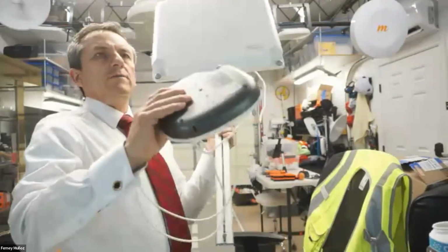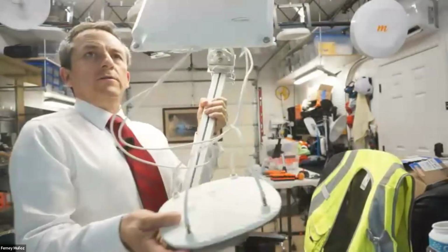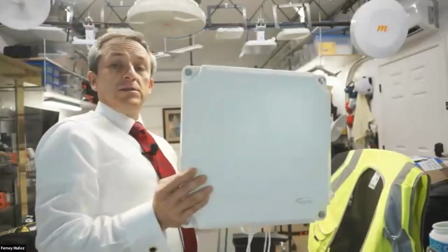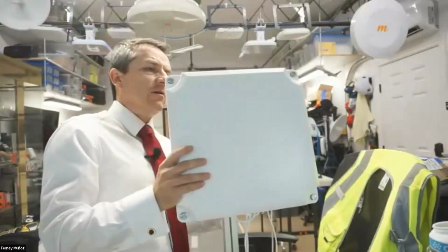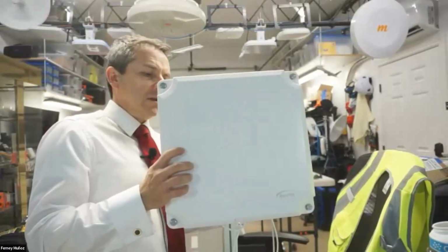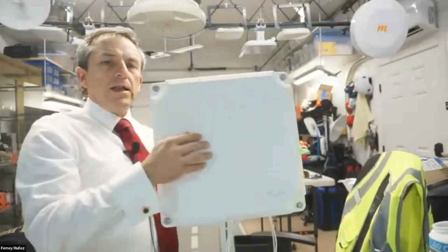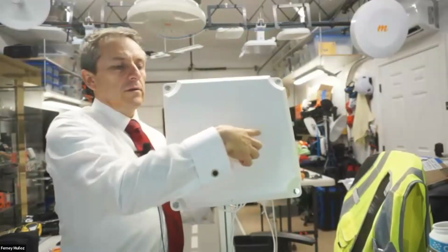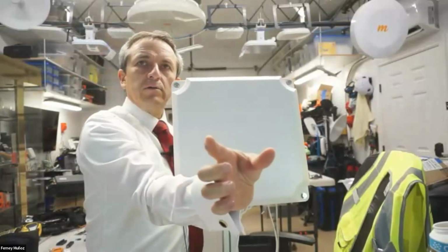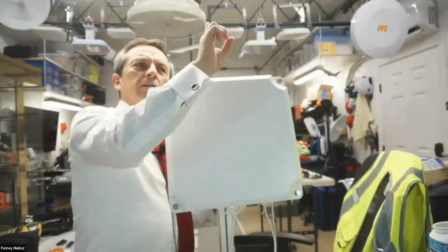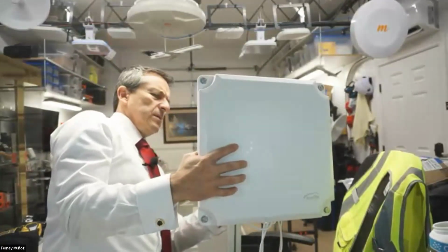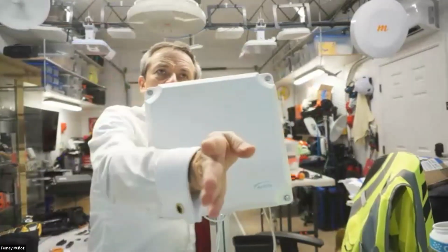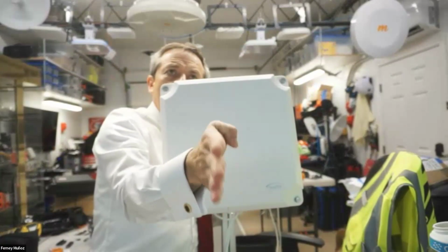Access point. Of course, you have to figure out how to mount the access point. Then you have cables. Then you have connectors. Then you have the antenna. Okay. This is one of those antennas we have in the picture in that warehouse, and one of the antennas we're designing. This one is big. It has a 15-degree horizontal. This one is basically like this, really narrow. And it has 110 or 100. Here, I got this spectrum in the back. It has 120 vertical. So it's basically shooting like this, narrow, okay, like that.